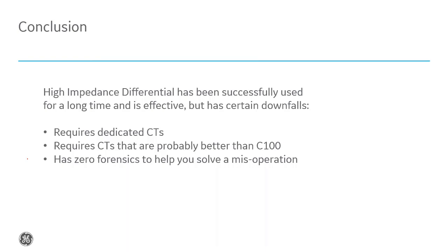Just so everybody's aware, Terry Smith and I both prefer low impedance bus differential. The problem is you've got to bring all the CTs individually back. But we can do oscillographies, we can see waveforms, we can see exactly where the fault is and what occurred on it. I can also use different size CTs.